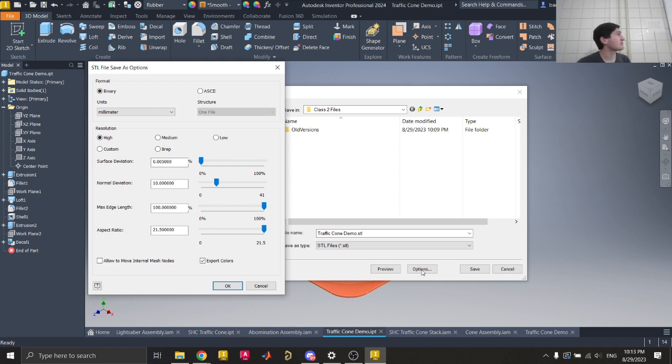So there's that. One thing that's important to do if you export to an STL file, especially if you have a fresh installation that you haven't messed with any of these settings yet: by default, your STL export settings are probably going to be selected as this BREP option. What can happen with that is if you ever have a 3D printed part that has circular or curved geometry, it's kind of a low resolution version. It turns into a bunch of polygons. So you can see basically it segments it into a whole bunch of lines rather than an actual circle.